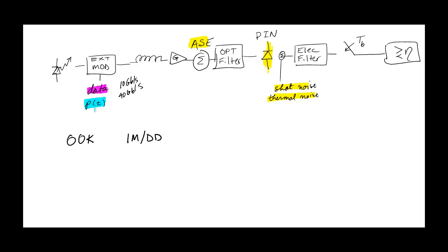We'll consider first a rectangular non-return to zero pulse shape. We'll also examine rectangular return to zero with 50% duty cycle. We're halfway through the bit interval, the rectangle transitions to zero. Since RZ rectangular pulses are half as wide in the time domain as the NRZ rectangular pulse, the RZ pulse will occupy twice the bandwidth in the frequency domain.